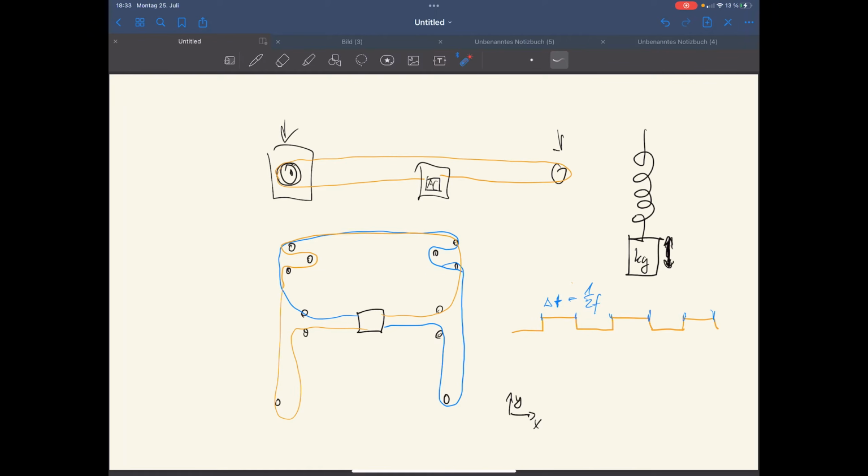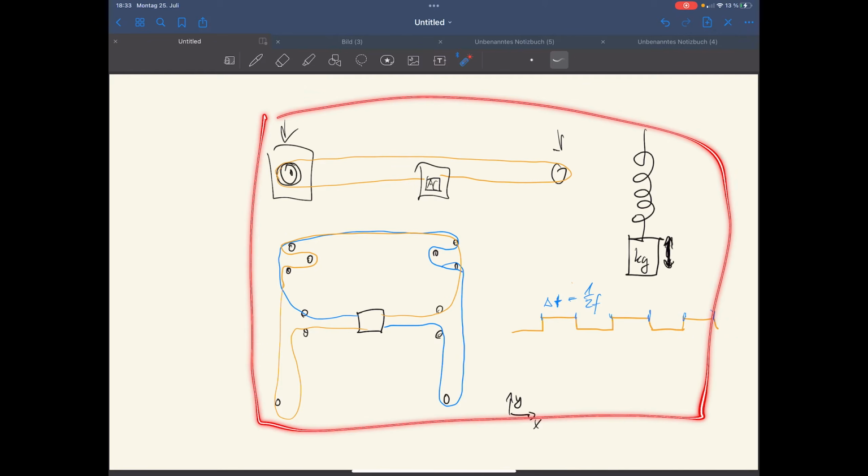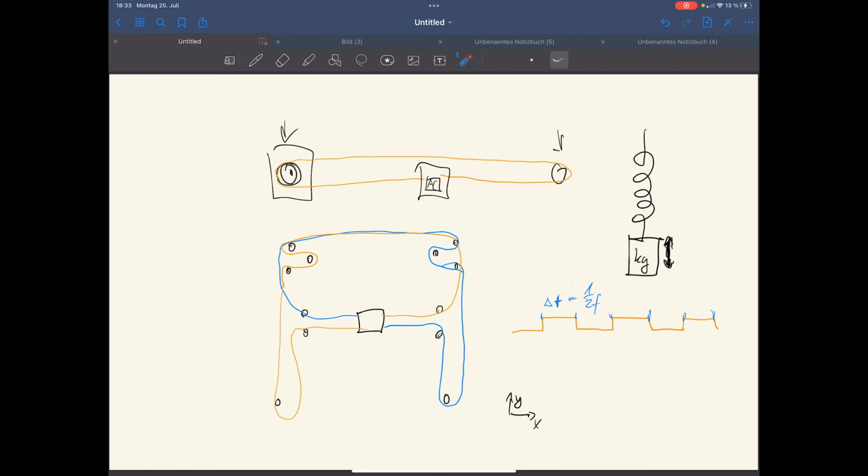And this is something to keep in mind for later, because we can see the smoothing does not only depend on the input shaper settings itself, but also on the printed geometry. And I will talk about that later in a little bit more, not in a lot of detail. But that's basically all you need to know. And the input shaper just tries to avoid specific frequencies we measured before.